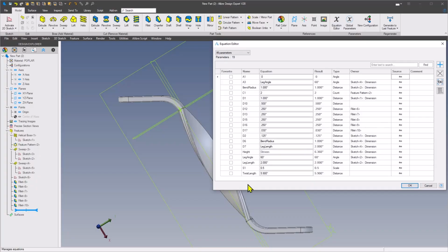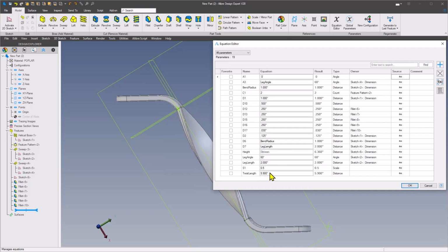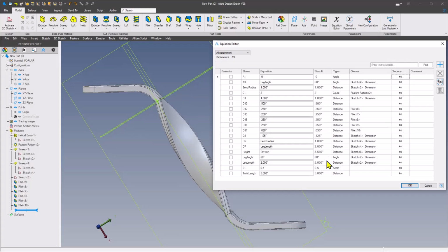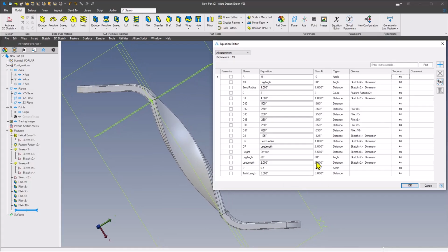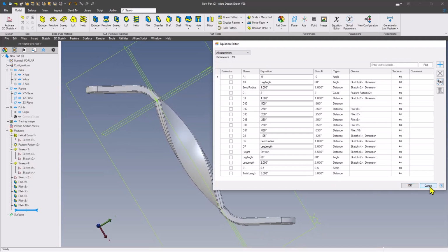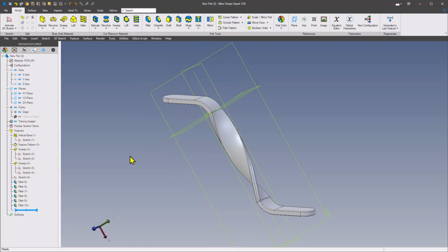But when you do that, take a look at your driven length. Now you're changing your height here quite a bit. So now you have to come back and change your twist length. If we come back here to 5 and okay that, our height is now 5.58. So now your twist length is going to be less than 5 to get back to your 5 inches high or whatever. But by playing with these values in here, you'll be able to adjust the height of your part from face to face, and that should give you a part that you can use.